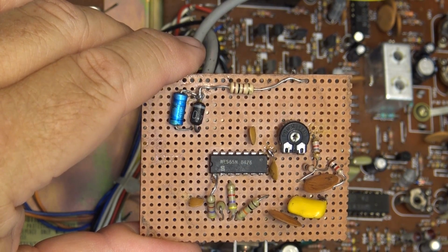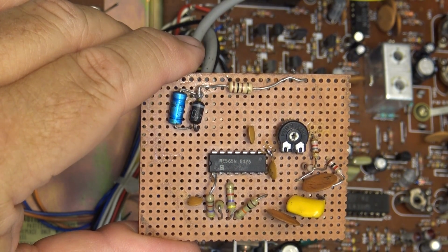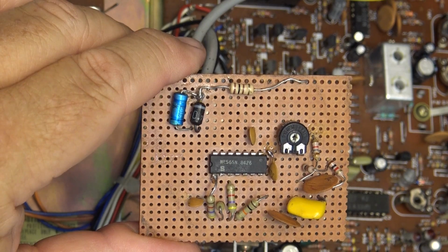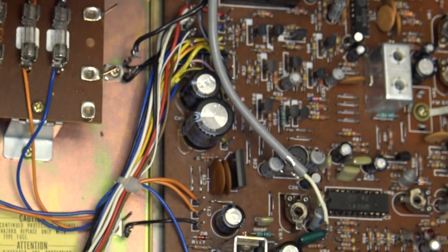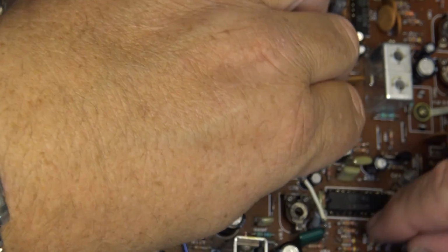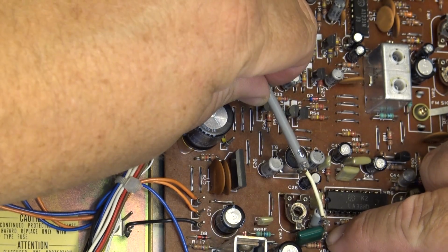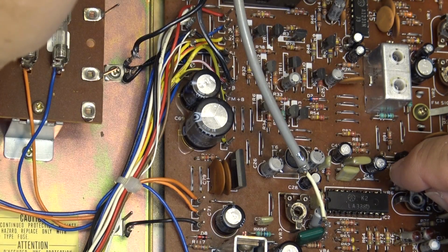It's not that complex, the circuit. It's actually very simple. The hardest part is actually adding it to the radio, because you need to find a baseband output. And that, in this case, is right here. I just tacked into this little resistor down here. And how I found it is I just used my scope and looked for the baseband audio.